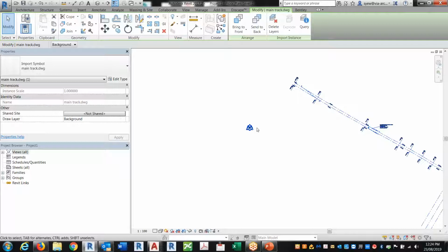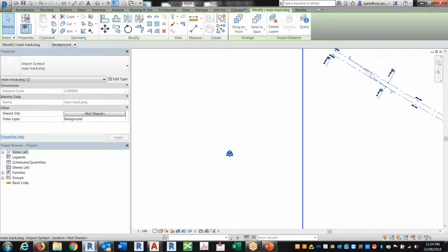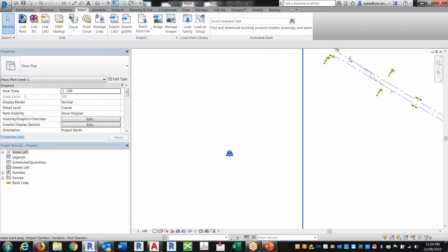So I would just say survey and 0, 0 should always be the same. Do not move your survey and 0, 0 to be different. Reason why I said this is because later on you'll notice that if you make those two to be different, it can confuse you and can cause so much havoc. Okay, just from my experience, just never do it.